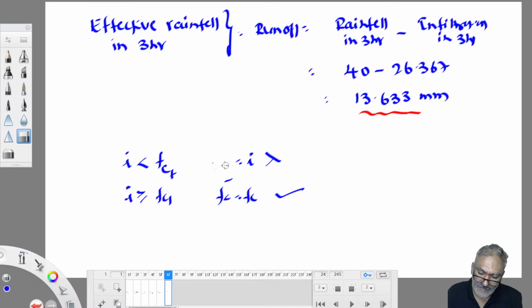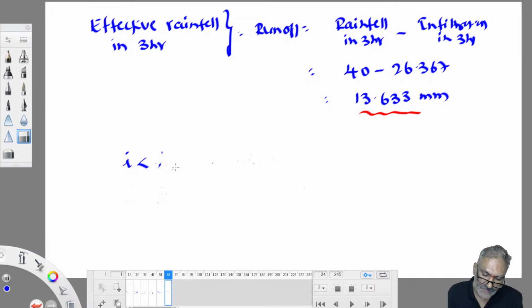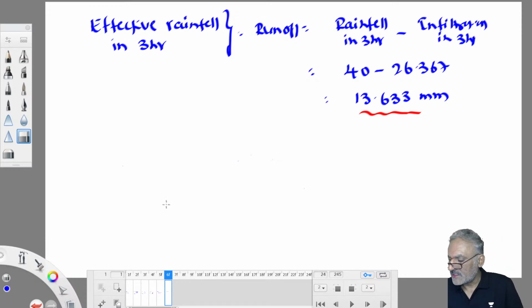Sometimes the actual rate of infiltration is the intensity of rainfall. Sometimes the actual rate of infiltration is the infiltration capacity. So that is where you're supposed to be careful. This kind of confusion is there with Horton's approach. To overcome this confusion, for our comfort and convenience, we have developed an equivalent procedure called infiltration indices. Understood? The infiltration indices concept came to overcome this confusion.